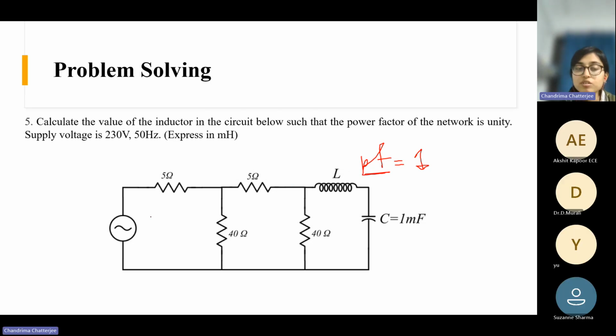Okay. So if this is the AC supply and there are some components, some resistance, inductance, capacitance. If it offers a pure resistive impedance, so if your Z is some resistance R, then the current will be exactly in phase with the supply voltage, and it will be something like this for a pure resistive load.